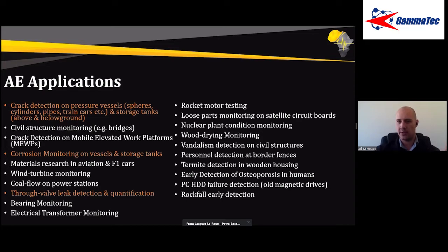All right, there's quite a few questions here. The first one I saw is, how does sludge affect acoustic emission in storage tanks? That's a very good one. If there is a bit of sludge in a tank, that's not an issue. It will throw out our location a little bit and decrease our sensitivity. But in general, we acquire 10 decibels below what we evaluate. So if you have sludge inside your tanks, as long as it's not too high, we can still detect it.